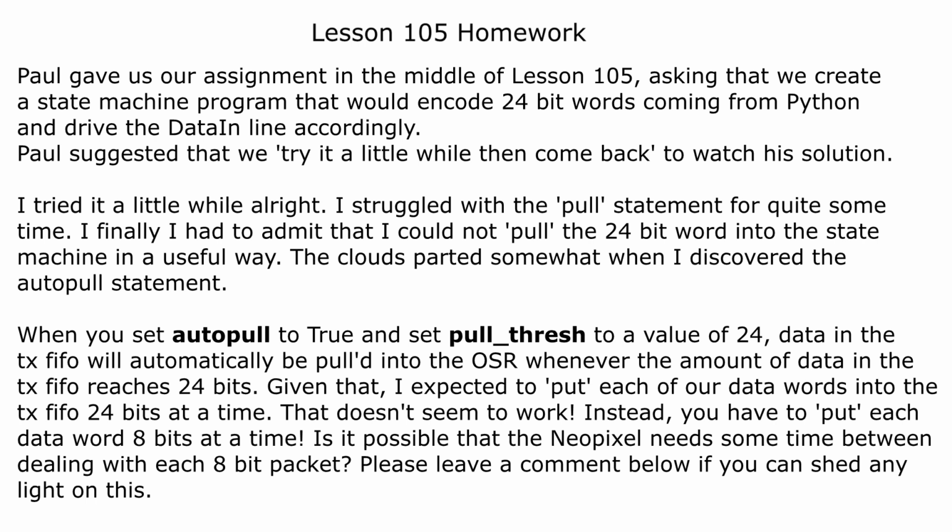I struggled with the pull statement for quite some time. I finally had to admit that I could not pull the 24-bit word into the state machine in a useful way. The clouds parted somewhat, though, when I discovered the auto pull statement. When you set auto pull to true and set pull thresh to a value of 24, data in the TX FIFO will automatically be pulled into the OSR whenever the amount of data in the TX FIFO reaches 24 bits.